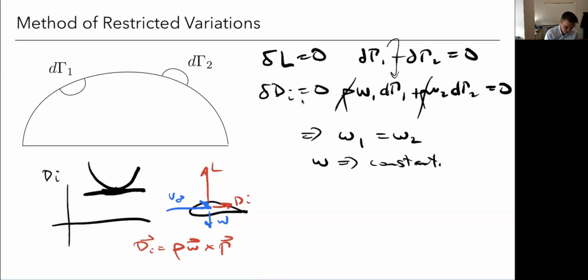So this formula, right? If you remember Kutta-Joukowski, if this is V infinity coming in, gamma's to the right, so V cross gamma gives me a force up, that's my lift. Well, winglet's gonna be the same.